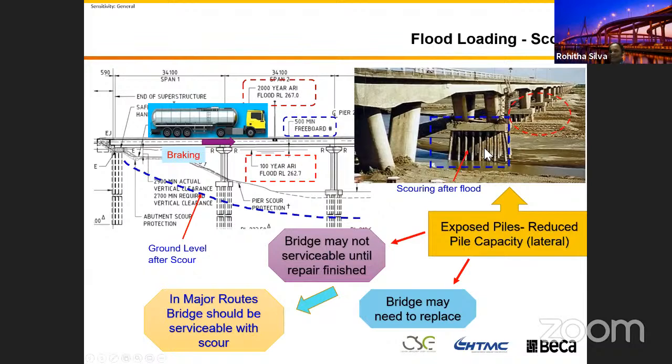And then the bridge is always subjected to a massive longitudinal load. You saw that one in the Eurocode as large as 900 kilonewton, and in the Australian standard as large as 1,200, and it will be multiplied by 1.8. You will see them later.